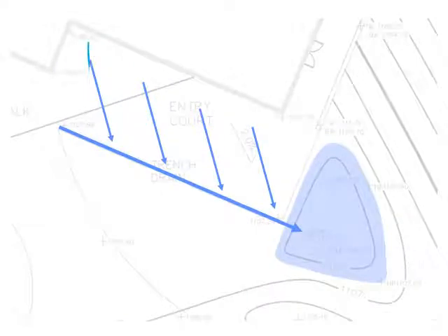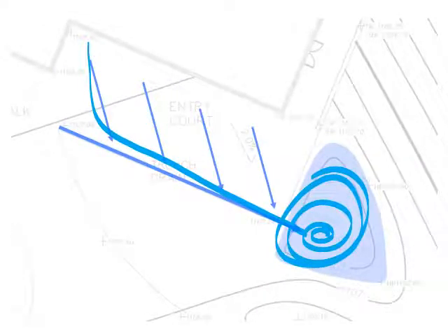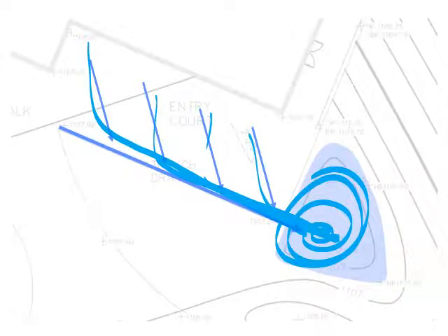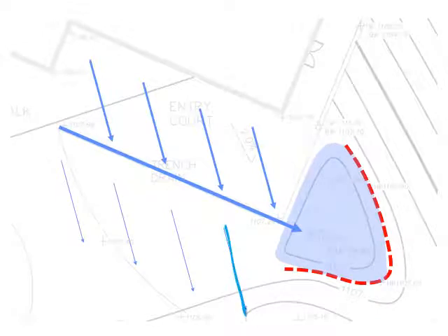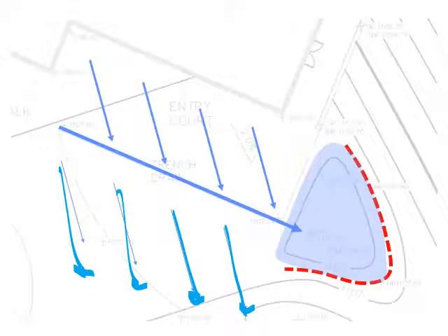Once we have this water diverted, it's going to start to fill up the retention area that you have designed down at the end. Once again, you're going to create a berm that keeps that system from overflowing downhill. As a result, you're going to have a smaller amount of water on the backside of the drain, or the downside of the trench drain, that can then be diverted again into a smaller retention area.